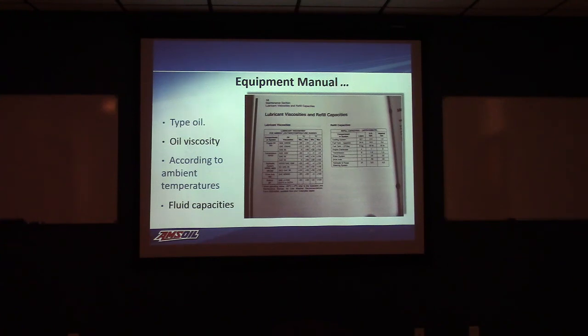What do they usually do? They'll usually define specifically what type of oil goes in what piece of equipment, what component on there. Is it a motor oil? Is it a hydraulic fluid? Is it a gear lubricant? If it's a gear lubricant, is it an extreme pressure product or just a light grade type oil? It really will define for you what type of oil.